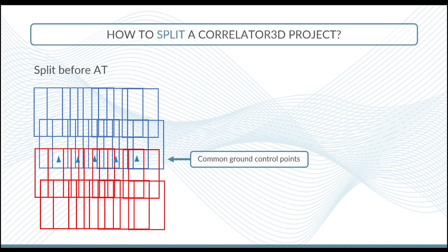That would be another way where you could split into different aerial triangulations. I think what you have to remember is that the challenge, if you split the aerial triangulation into different blocks, is to ensure that you have a good accuracy between all these different blocks.